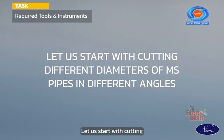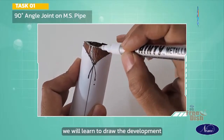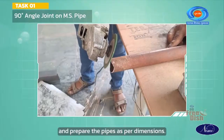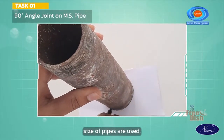Let us start with cutting different diameters of MS pipes in different angles. For this, we will learn to draw the development of a 90-degree T-branch, cut and prepare the pipes as per dimensions, set a 90-degree angle of the branch pipe using the tri-square, and ensure the correct size of pipes are used.